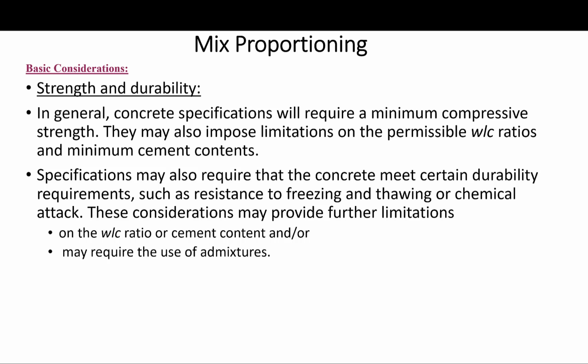It must be remembered that even a perfect mix will not perform properly unless the proper placing, finishing, and curing procedures are carried out. Again, we go back to concrete practices in the field. Sloppy or less than perfect practices will compromise the best mix design out there. That is a message to our field engineers and construction personnel: always pay attention and follow the procedure.